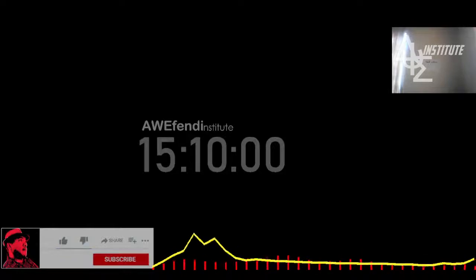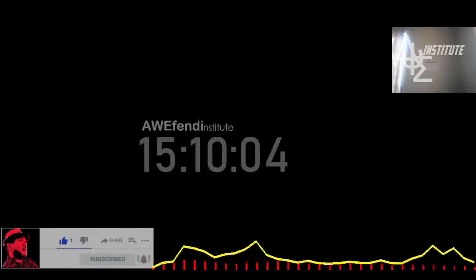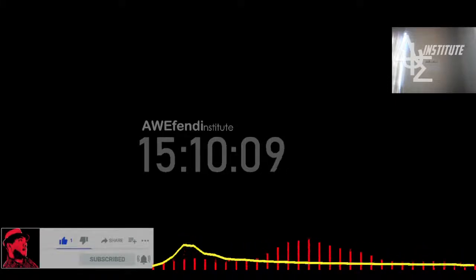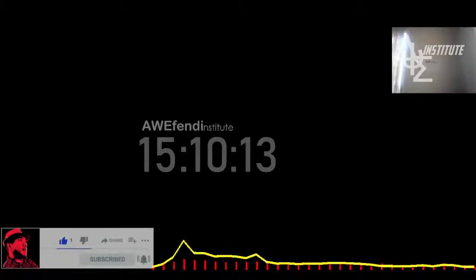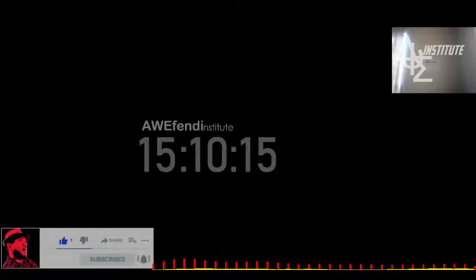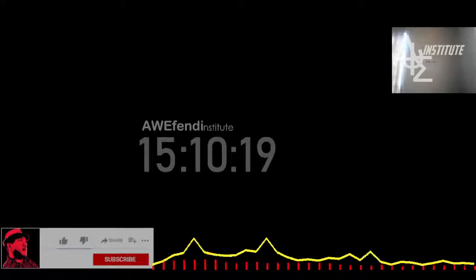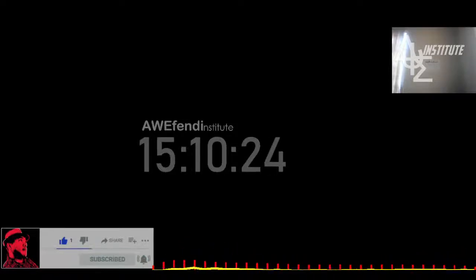Basically, this is a 3D rendering of temperatures. We can also just set outer temperatures to see a little bit how the warmer flow coming in from the top is contained to this upper region of the pipe on the outlet, meaning that this piping is probably getting warmer on the top compared to the bottom. So you're going to have a temperature gradient, maybe something that you want to take into consideration.